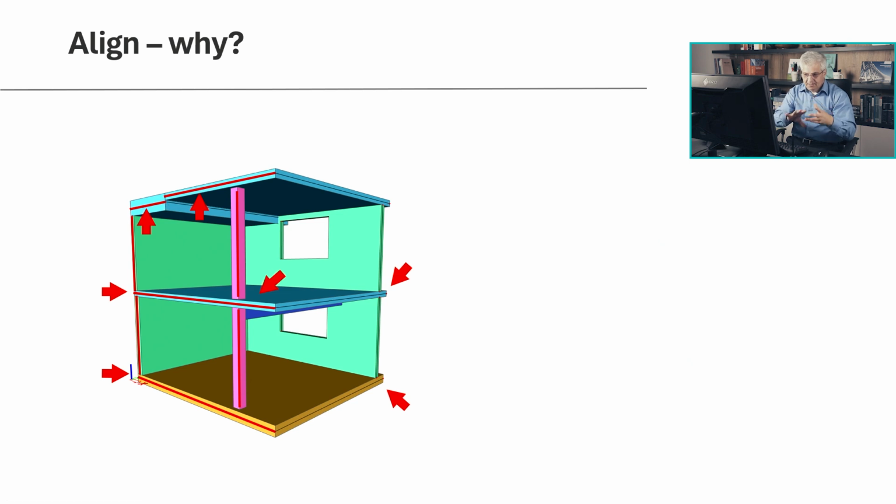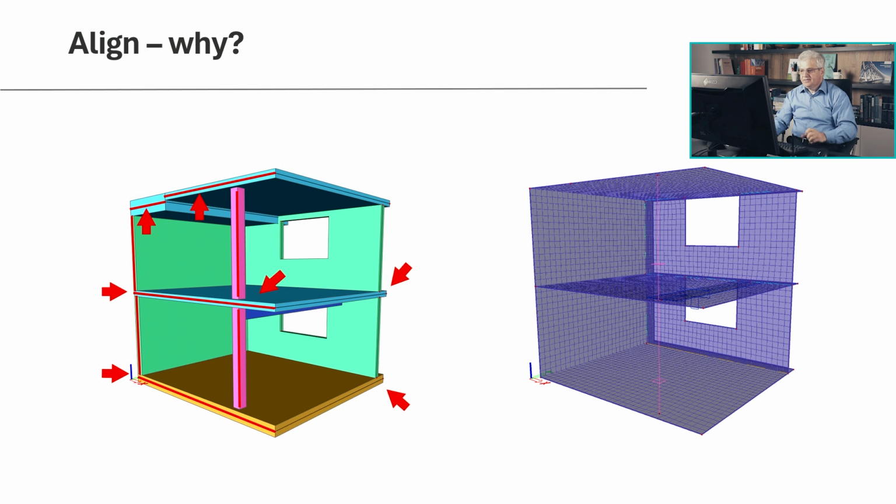The next step which is done is to move the nodes. You see the wall stops on the bottom on your slab, and also the column, and they have to be moved, and also the walls are not connected in the corners. And you have also these ribs, they are in 3D, so you have to move them in the plane of your plate and convert them from standard member to a rib. So all these things can be done in the alignment. And then if everything works, you get a nice 3D model which you can calculate.